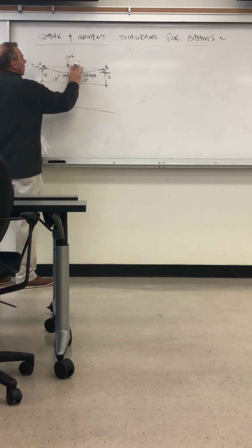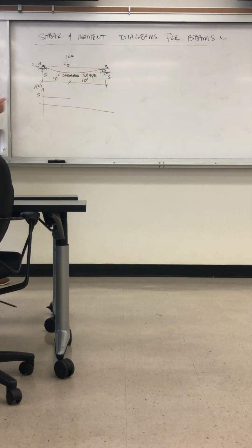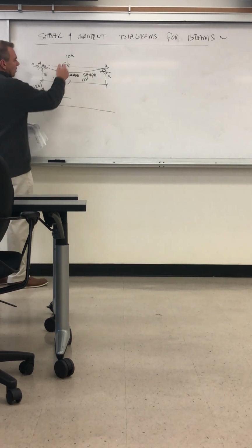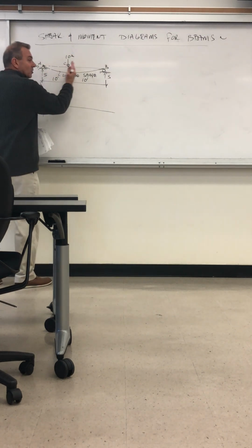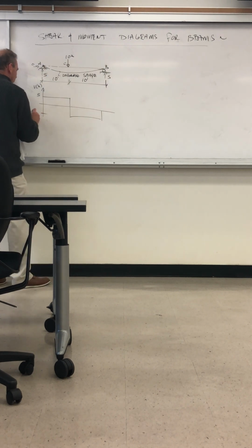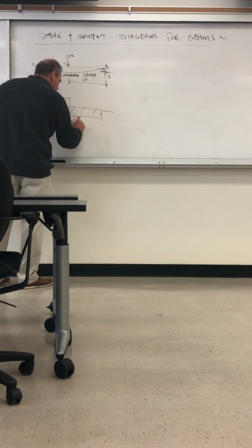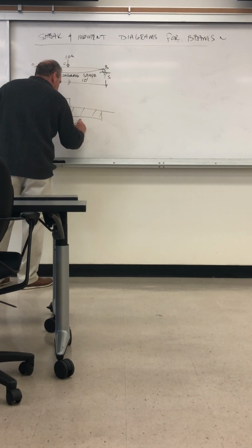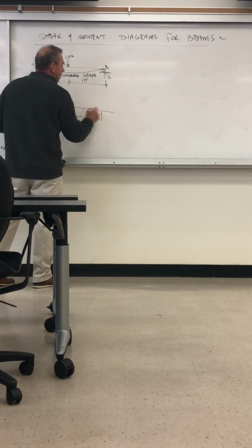And then now imagine, it's still true, you're pushing up on every cross section as you go along, 5 kips. You cross C and it's 5 minus 10, so it's minus 5 kips. It still feels 5, but it's pushing down now. Like if this 5 wasn't here, it would just be 10 kips down at each cross section. But you have to sum everything as you go across. Right? So here it drops to minus 5. And this is the shear diagram. That's A, C, and B.